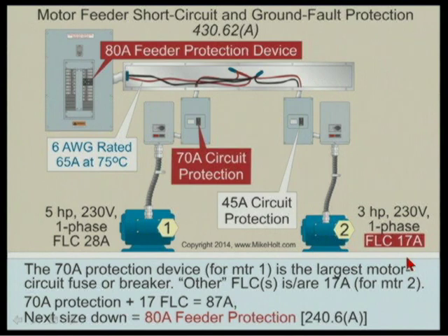And I'll go there. There's a possibility that if I'd used a different current over here, this could have come out to be, let's say, 68 amps. Well, if it's 68 amps for the branch circuit protection, you'd have put a 70 amp protection. But some people would have thought that you take the 68 amps plus the 17. Right. And I knew that's what you were leading up to.